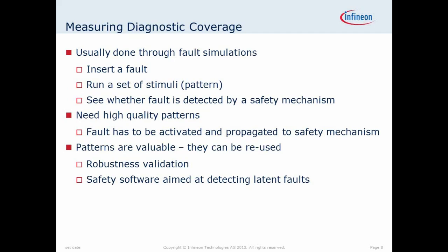This sounds okay, but in practice it can be difficult. You need very high quality patterns. If you have a fault deep down in your design, you need a pattern which is going to activate that fault and then allow it to propagate to an output, or to a safety mechanism.